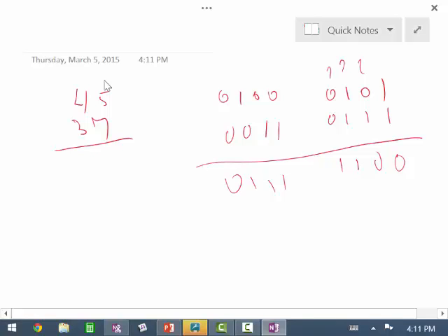Now we know that this is not a legal BCD number. We know that that is true. So if that's the case, if we use that last instruction there, that decimal adjust DAA, immediately after our add, the microprocessor knows to adjust this for a decimal add. So it would automatically look at this and see that I have an illegal number.